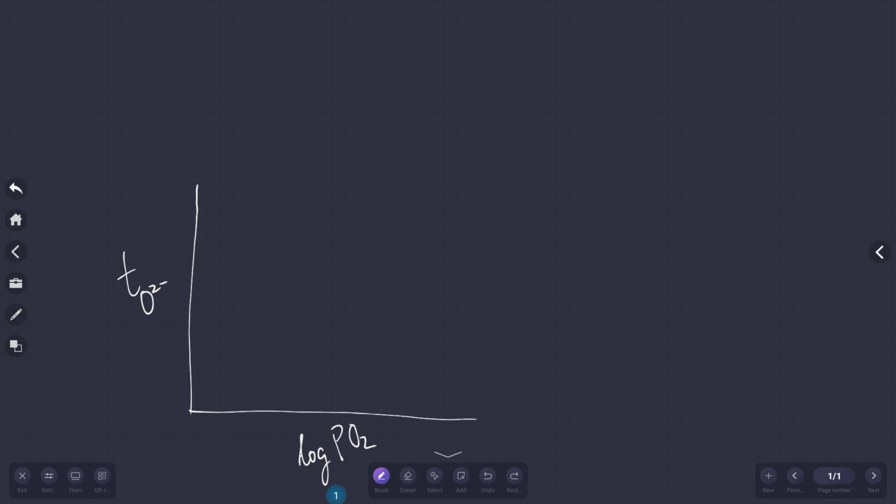So at low PO2, you can see that it's n-type. So when I have low PO2 n-type, what is the transference number for oxygen ion? It will be 0. Because n-type is all electronic, 100% electron. So this will be 0. If you move into the mixed region now, you will have electronic n-type as well as ionic.